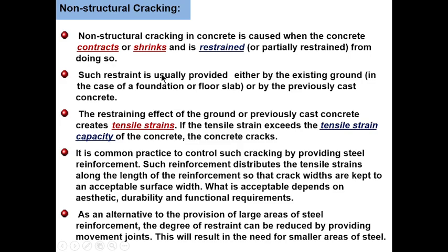So when concrete wants to shrink or contract and there is a restraint against it contracting, you will have those cracks. Such restraint is usually provided either by the existing ground, in the case of a foundation or floor slab, or by previously cast concrete.